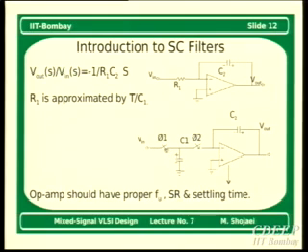Therefore, the entire charge which is stored here will be transferred to capacitor C2, and this charge will be transferred completely. We consider the time cycle T large enough so that the delay of this discharge, which is due to the finite resistance of this switch, is small enough that this capacitor will be almost discharged completely in C2.